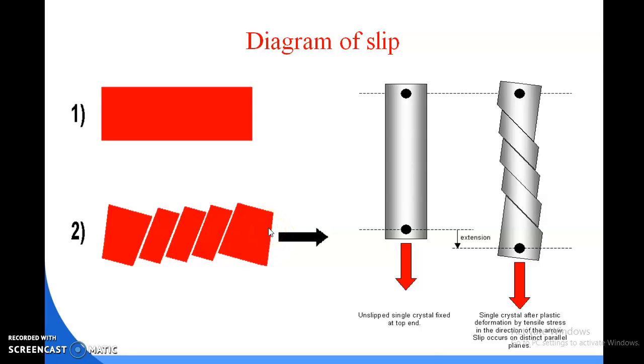Depending upon the type of lattice, different slip systems are present in the material. Specifically, slip occurs on close packed planes and in close packed directions. The magnitude and the direction of slip are represented by the Burgers vector. We have already discussed what the Burgers vector is. It is the magnitude and direction of the atomic arrangement of a crystal material. The picture on the right shows a schematic view of the slip mechanism, where the slip planes and slip direction in a crystal have specific crystallographic forms.